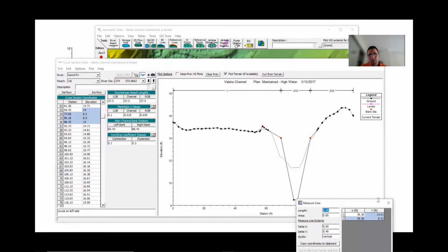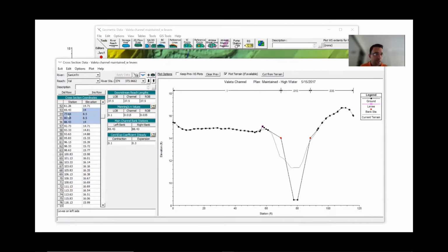And that's happening. So basically, this is, again, a manual process. You have a cross-section like this gray line. You edit points like this to enable a trapezoidal channel as is given to you in the as-built information. You can manually type it, or you can do it with a graphical method. At the end, you need to make sure that you're getting top width, bottom width, side slope, and maximum depth. So basically, this is how we get to this.